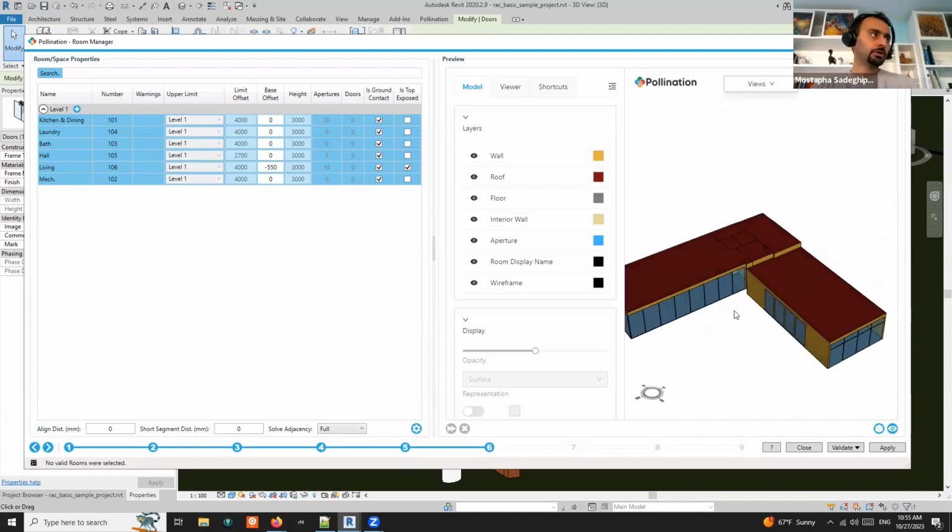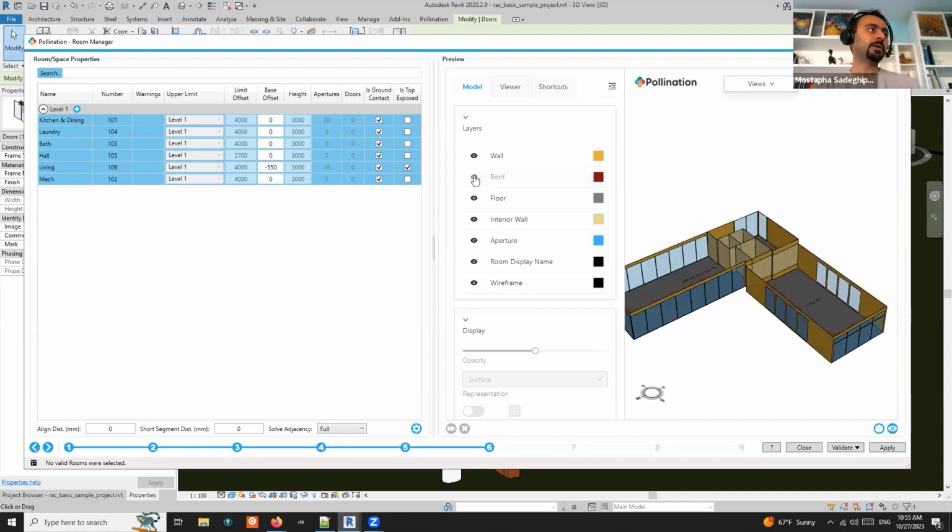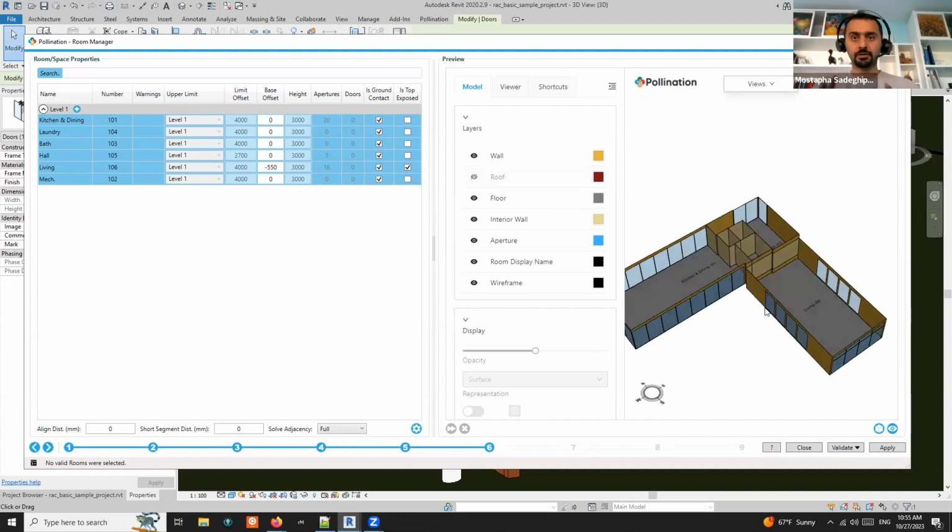So why am I showing you this? Because we have been very, very careful to tell people when is a good time to run energy simulation from inside Revit and feel like you can rely on it. And this solve adjacency is a very important part of it. So right now in the public release that we have, the solve adjacency is only working for the extruded mode. In a matter of weeks, we will have the one that is for the full 3D model.